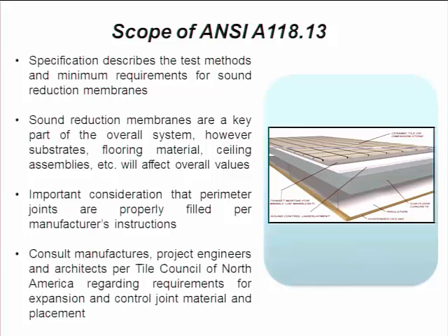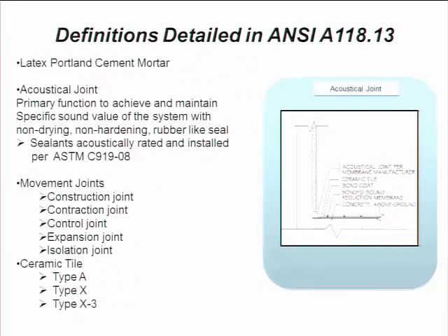The important consideration also to mention in this specification is that the perimeter joints are properly filled per the manufacturer's instructions. You can have the best system out there, but if you're not dealing with the perimeter joints properly, you're defeating the purpose of using the membrane that you are using. Always consult the manufacturers and architects regarding the requirements of expansion and control joints. I'm not going into much detail there, as that's a common situation that is carried through with the soundproof membranes.